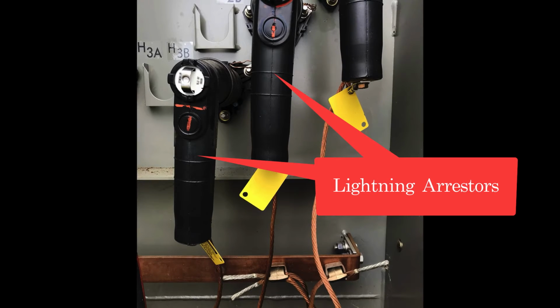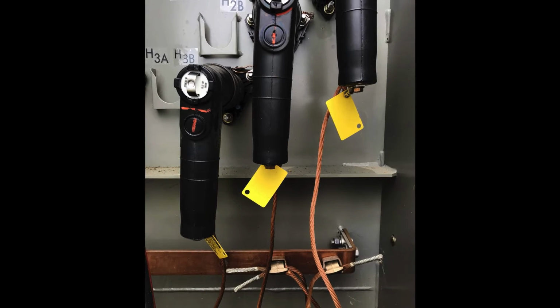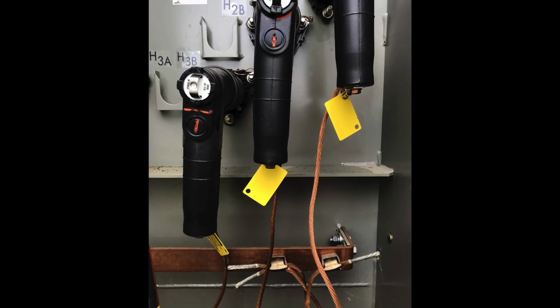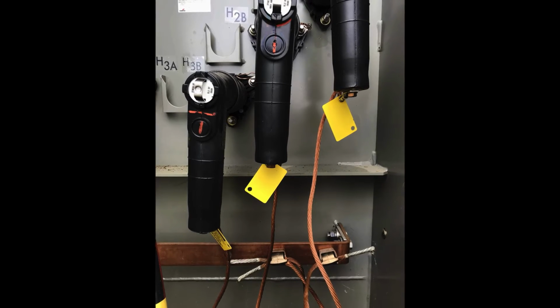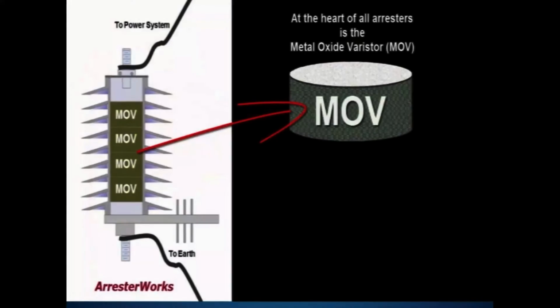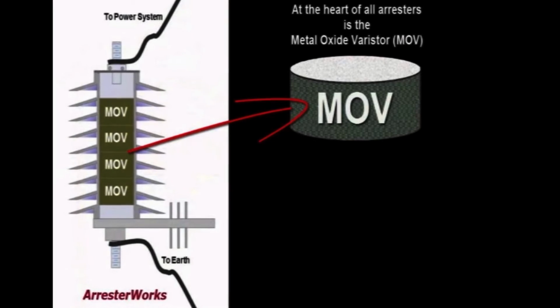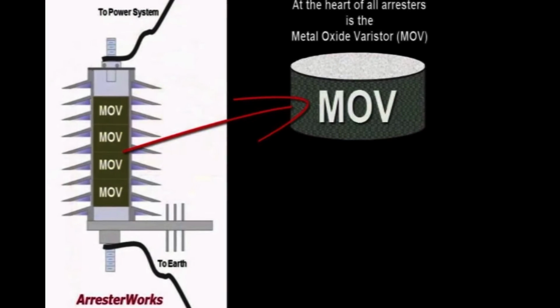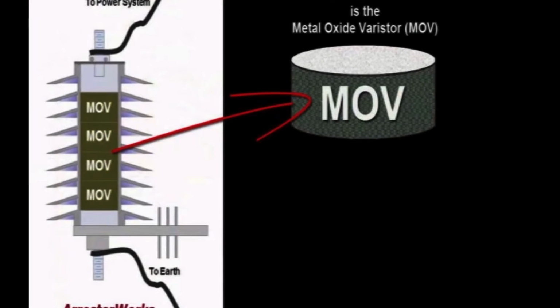These devices are usually installed on the last or the first transformer in a chain. They serve to protect the transformer from very high voltage spikes such as those caused by local lightning strikes, which can momentarily expose the transformer to voltages of 100 kV or more. They link the primary windings to ground through a stack of metal oxide varistor pucks that will create a ground path when excessive voltage is present in order to dissipate that voltage to ground.